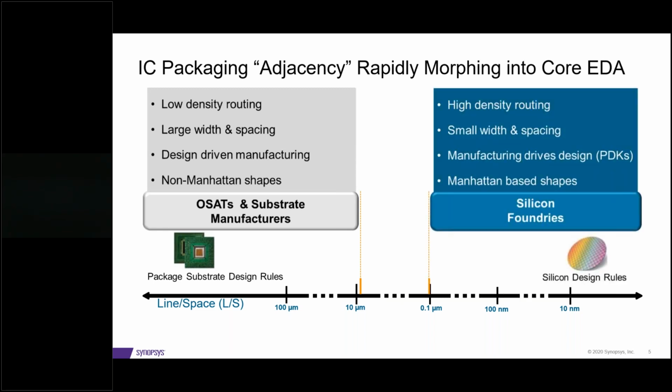Whereas in a semiconductor world, we're looking at much finer traces. And that's the reason we see this window of opportunity between the packaging substrates of today, as a generic monolithic packaging, compared to what silicon can provide. And that's why we see the introduction of the silicon interposer coming into market more and more, trying to fill up that gap for applications that need a denser number of wiring connected between devices.